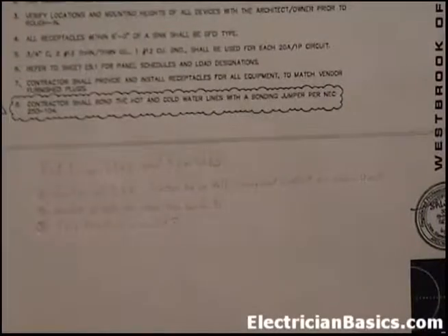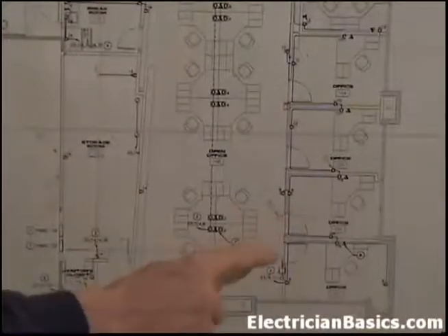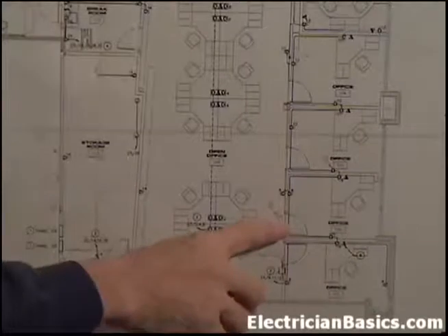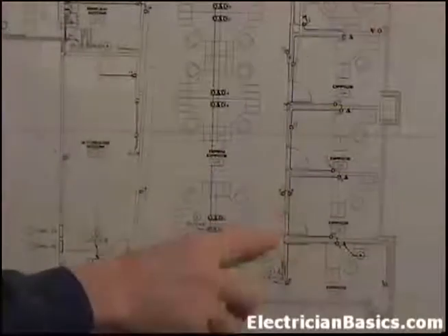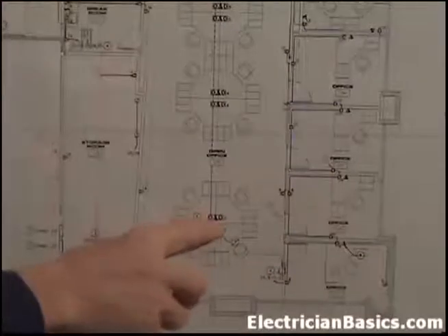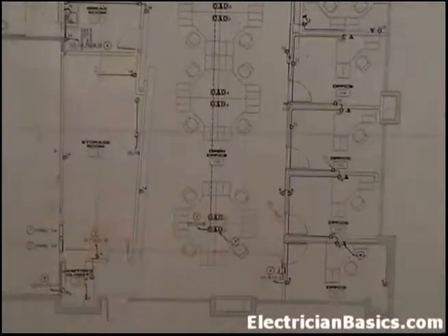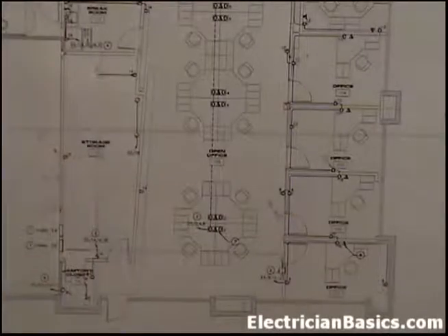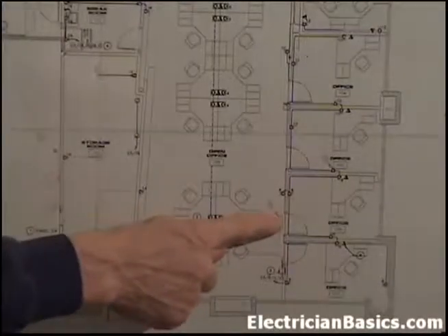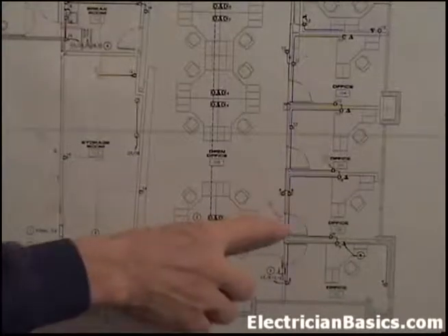And if we go back, we're going to take a closer look at that and see what they did. Okay, so from our keyed note 1, we were saying that the junction box was on top of this wall, and then the conduit went through the wall underground to the Walker duct. Now remember, dotted line for conduit is underground, so we're going to show that on our red line diagram as well.